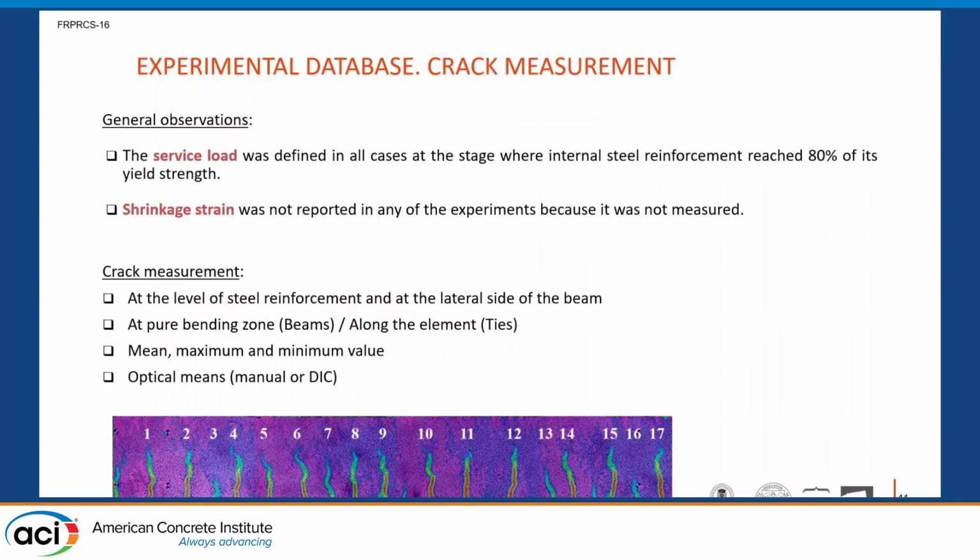And how all these elements were measured, we fixed the service load at 80% of the yielding of the steel. And another very important thing is that the shrinkage strain was not reported for any of the tests, so we could not have this value.